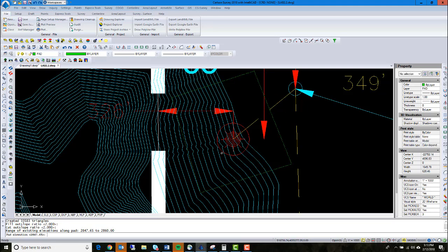So you typically hold a standard pad elevation. You could go around and actually put elevations on each one of your little nodes there, and you can put ones in the center here if you want to make a crown, and sometimes they'll do that so rain will fall that way or this way or that way or that way. You can design it that way.